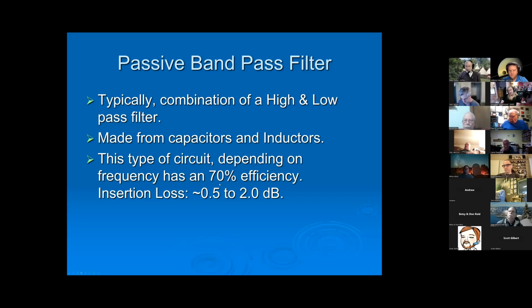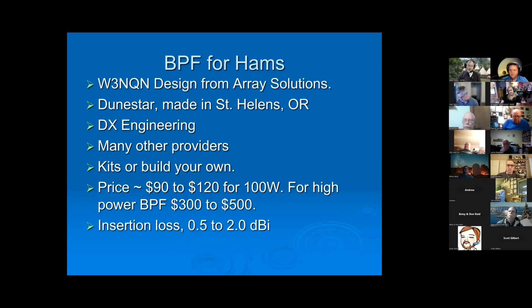Bandpass filters that have steeper skirts and are more efficient in giving you good rejections are going to have higher insertion losses. So just think about that as you get better and better bandpass filters that do a better job of filtering out stuff you don't want to listen to. You also have to pay a penalty by a little more insertion loss.